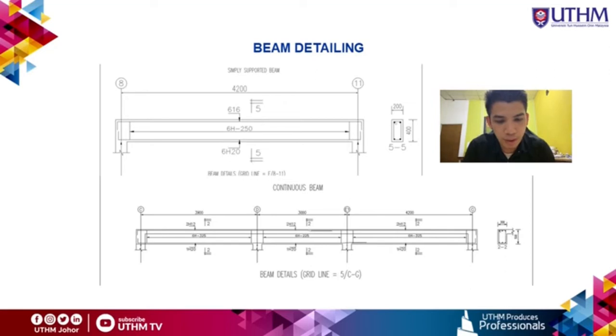The values of the dead load, live load and other information are obtained by referring to BS and Eurocode standards, and also the material catalog. The dimension of the reinforcement bar is assumed to be 20 mm for the tension zone, 16 mm for the compression zone and 16 mm for the link. The value of the design parameter obtained from the calculation is 44 mm.